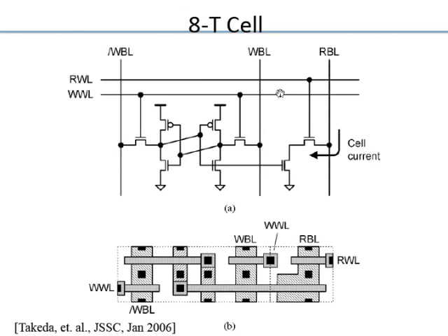Of course, now you see, what you have done is you have increased the area. But the cell current no longer flows through the cell, it just flows out here. It doesn't disturb the cell. So the noise margin of this cell during read is the same as that during hold. So it has better noise margin. The cost is you have extra area, because you have 2 extra transistors, 1 extra vertical wire and 1 extra horizontal wire. Of course, this does give you 2-ported operation.